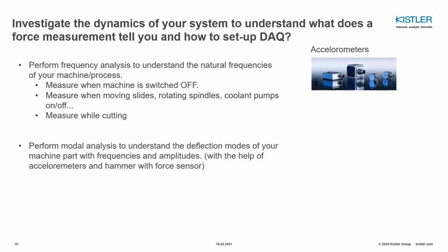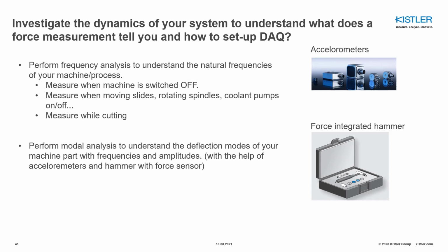And you can take this one step further. You can perform modal analysis to understand the deflection modes of your machine part with frequencies and amplitudes, with the help of, for instance, accelerometers and a hammer in this case. So when you follow this and really understand and investigate your system, then you will really understand what is what when you make the force measurement. And of course, it's also an important procedure for setting filters and sampling rate when you have this understanding.